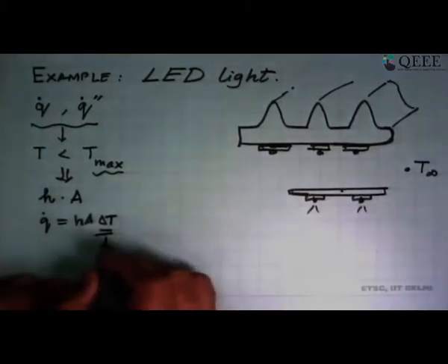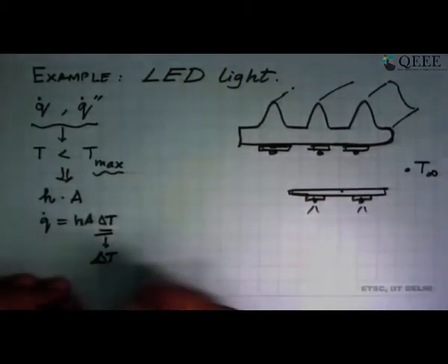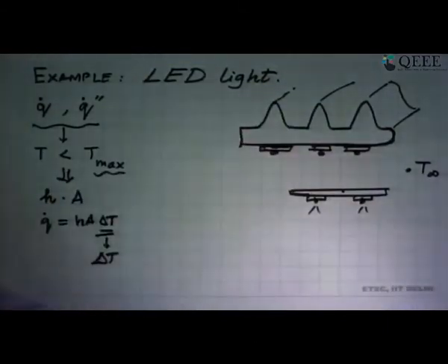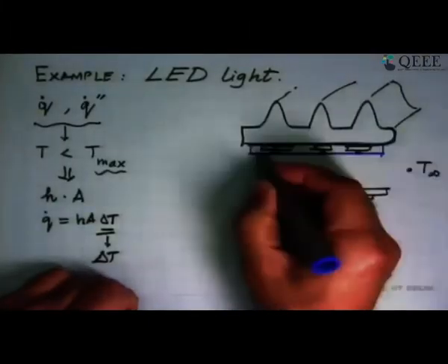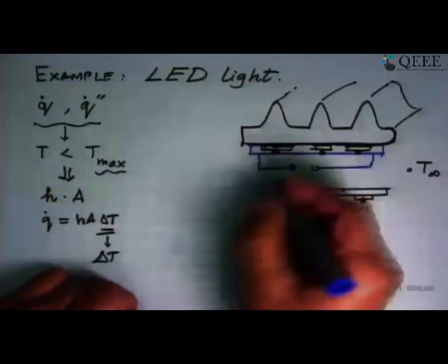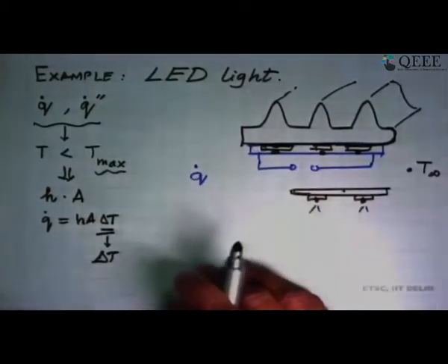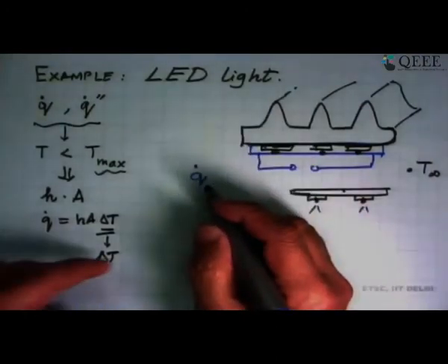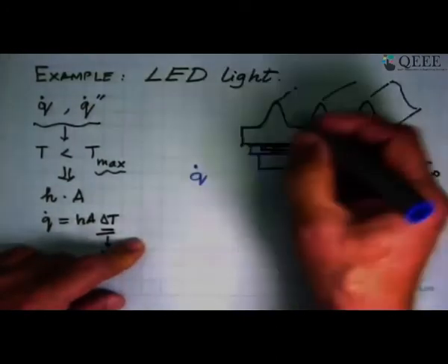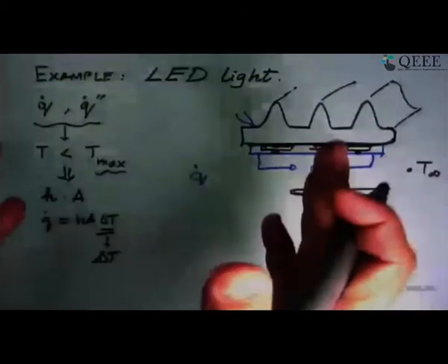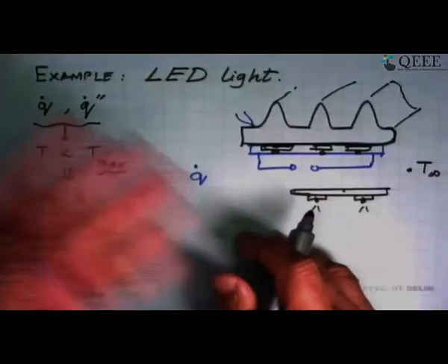We said that, okay, I am going to enforce a certain delta T, so I will design an experiment where I will not put this thing, but I will generate that heat by putting an electric heater below this. So we'll put an electric heater and measure the power that we give to this. So Q dot is known to us. We put a wattmeter there or a voltmeter and an ammeter, and if you have put DC supply, V into I will be the power there. And then I want to measure the temperatures of this. So we have an option of either fixing some thermocouples on this or taking an infrared picture of this, and from there we go back and get all the temperatures.